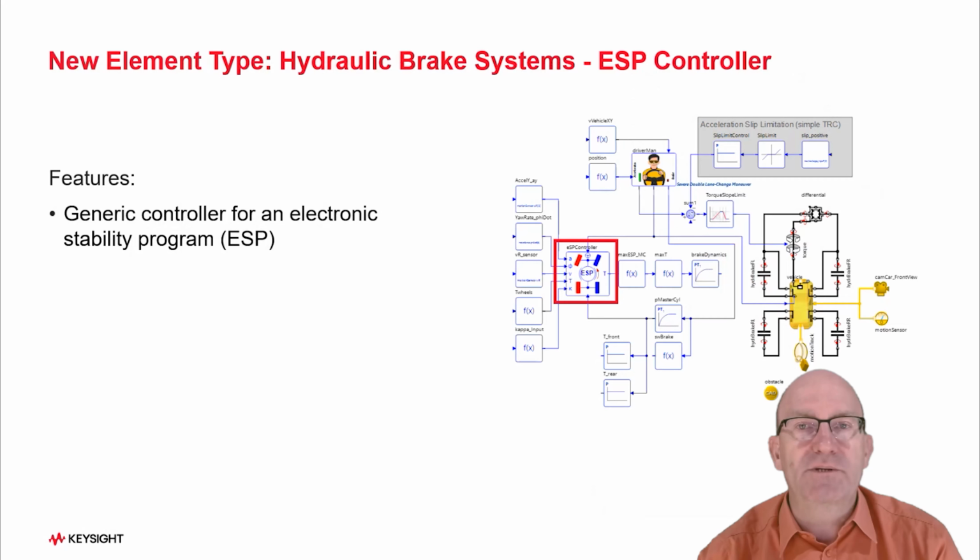Okay, so moving back into my presentation and switching topics, I now go into driving of vehicles, and there are a few interesting developments. Maybe the most interesting one is the introduction of an ESP controller into SimulationX. It is part of the hydraulic brake systems, and it is a very generic way of modeling a controller. So it's not like a specific device which you would purchase or which belongs to a certain type of vehicle or manufacturer, but it's an implementation of the generic functions which you would expect from an ESP controller. So that means monitoring the vehicle and providing input in terms of brake torques to the wheels so that we know how we want to control our vehicle.